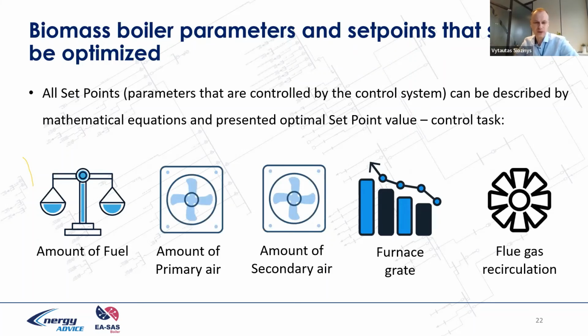Coming back to boilers in general, the digital twin solution is capable of providing you set points for fuel amount supply, primary and secondary air rate, furnace grate rate, flue gas recirculation. So in general, it's not just monitoring and collecting data and building mathematics with KPIs and some predictive maintenance elements, but it's also for the operators. It's a set point where operators can track these set points.